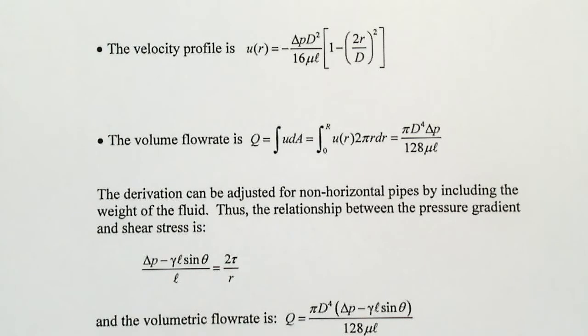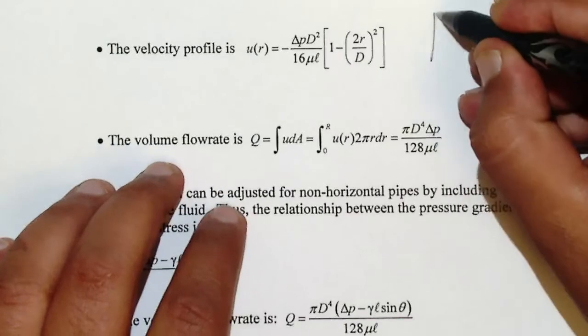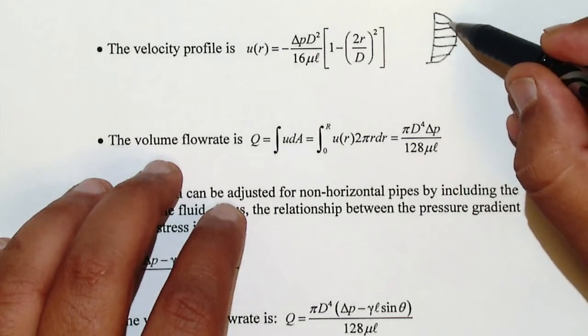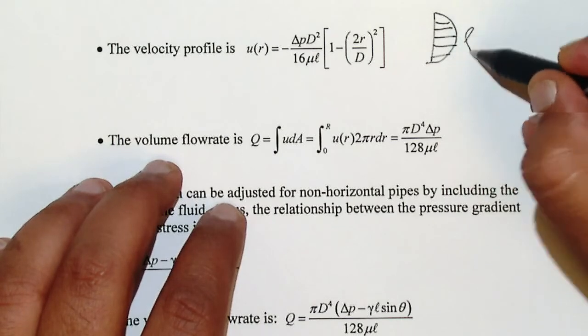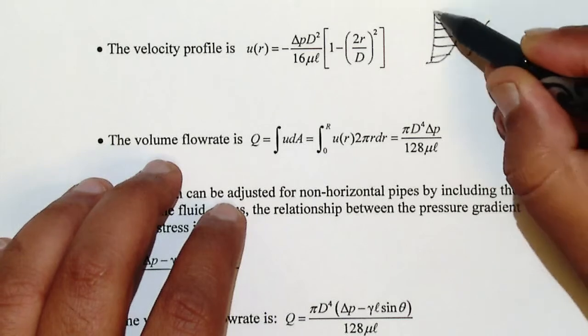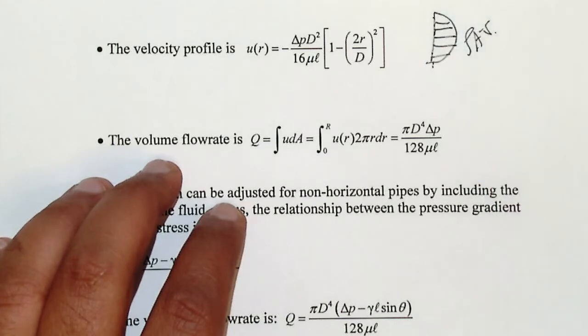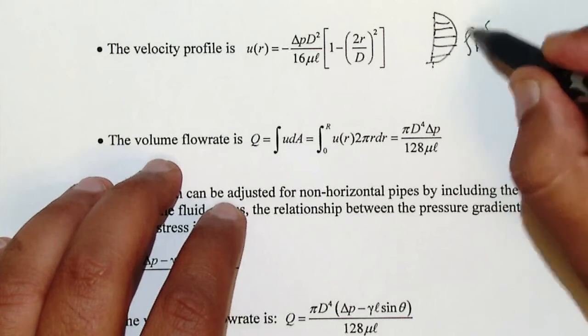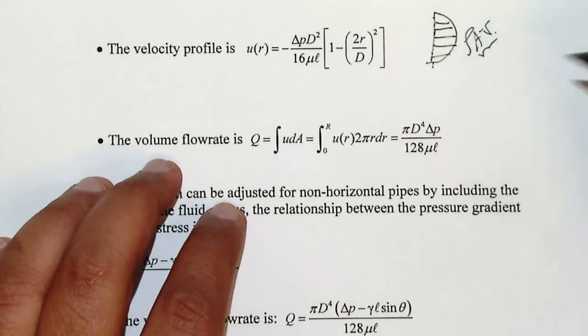After that, we can write the volume flow rate, right? Why do we need the volume flow rate? We need that to find the average velocity of the flow, right? As we talked about later, and also in the previous chapter, when the velocity profile is locally changing, if you want to find the Q, you cannot write rho A V, because V is changing at each point. That means you have to take the integral of that to find the mass flow rate or the volume flow rate, which is AV.